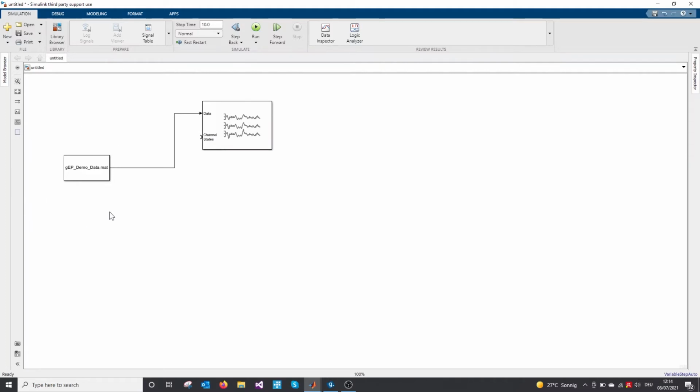Now, as we don't have an amplifier here which paces our Simulink model, we do need the real-time clock. So we're also gonna add the real-time clock block there. Click it and it's added. The real-time clock will basically pace down the simulation time to real time. Now I'm also gonna set the stop time to infinite to let the model run as long as we want to have it. And then we're gonna take a look at the data, at this EP demo data.